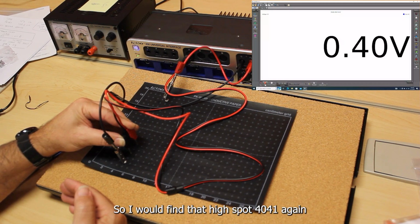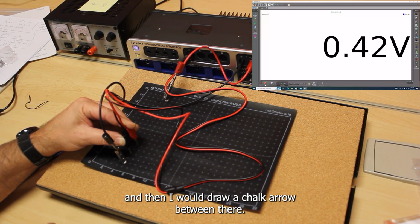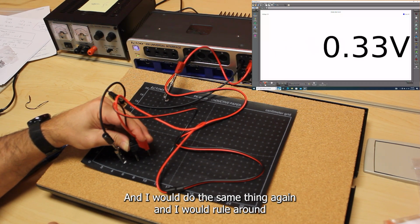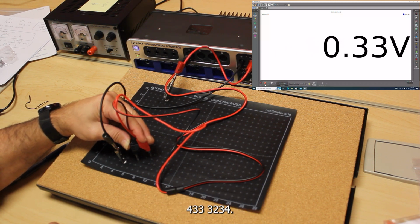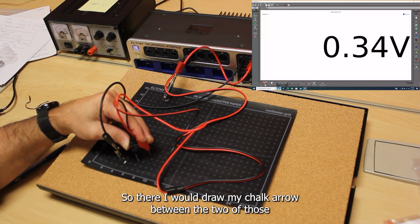So I would find that high spot, 40, 41 again, and then draw a chalk arrow between there. Then I'll move it to another point, maybe like this one, and do the same thing again. I roll it around, 34, 33, 32, 34, so there I would draw my chalk arrow between the 2 of those.